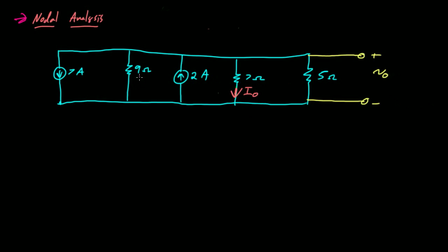And we are going to do this every single time we do nodal analysis. Essentially, the big equation that matters when we do nodal analysis is that the current that goes into a node is equal to the current that flows out of the node. You can think of this like a hose with a junction in it. If 5 gallons of water flows in one part of the hose, then we have to have 5 gallons of water that flows out of the hose.